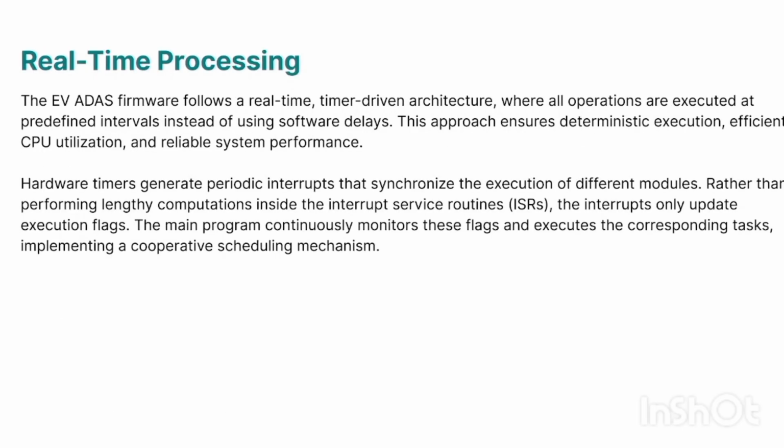Real-time processing architecture. Real-time execution requires strict predictability. The firmware uses a timer-driven architecture where hardware timers trigger interrupts to update execution flags. Complex calculations are kept out of the interrupt service routine. Instead, the main thread polls these flags to run tasks cooperatively.